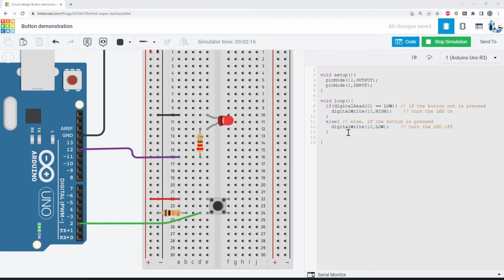Now, we'll use this opportunity to introduce a new programming concept. Imagine what would happen if I wanted to connect my LED to a different pin on my Arduino. I would have to change the number 12 in 3 different places in my code. This creates a risk that I could forget to change it somewhere and then get an error when I try to upload my program.